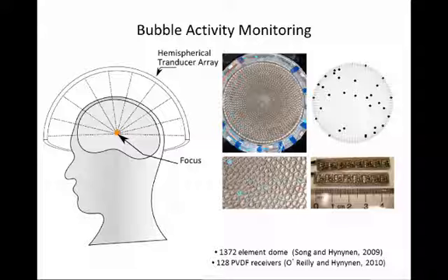The elements are designed so that they have a hole in the middle, so we could put a hydrophone in. We didn't have quite a large number of hydrophones, so we put in 128 hydrophones, and those were located in an optimized sparse pattern. We try to get the signal, to see if we can image the locations of the bubble vibrations.